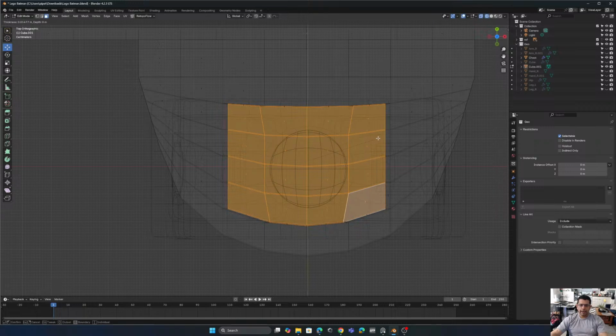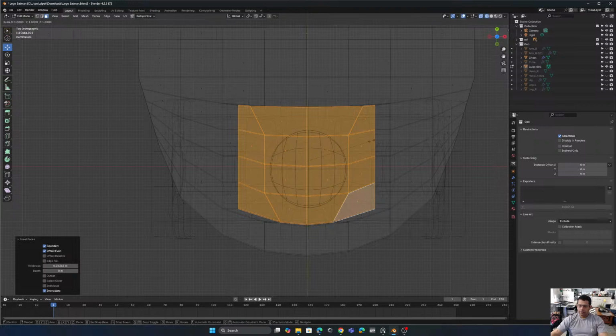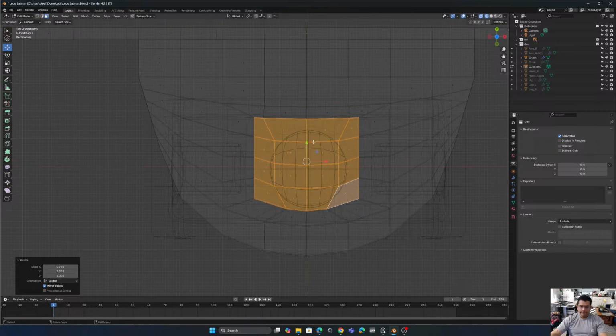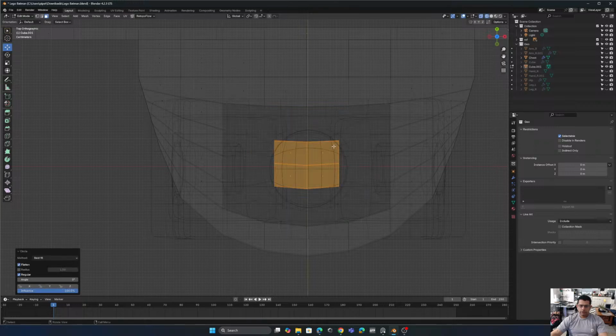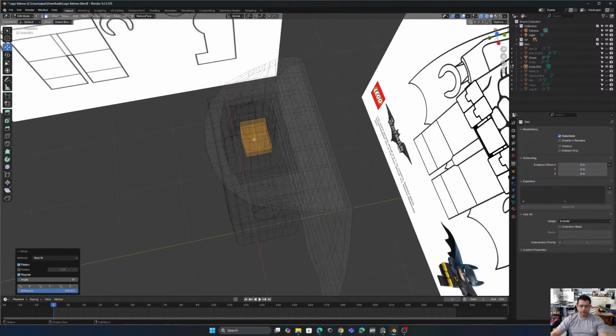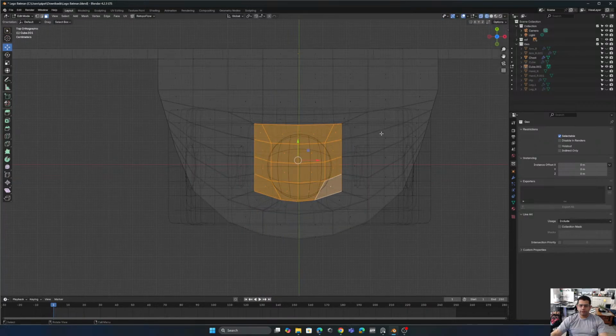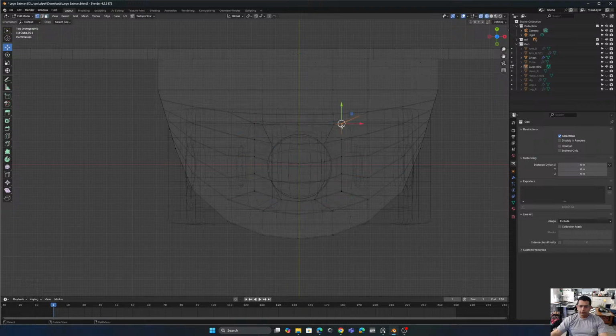Now insert with I, pressing the key I, scale it in y-axis, scale it in x-axis, circle. It's not working because we have a lot of different shapes, so we're gonna try manually. We're gonna go to top view, we're gonna go to vertices, and we're gonna move it manually to get a better circular shape.